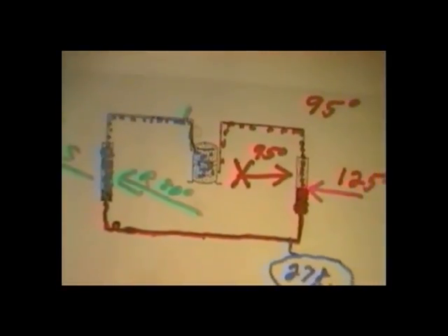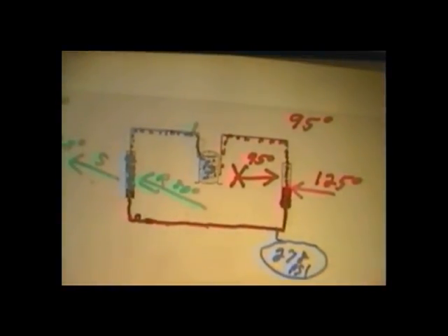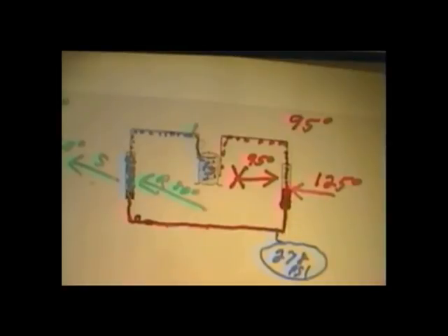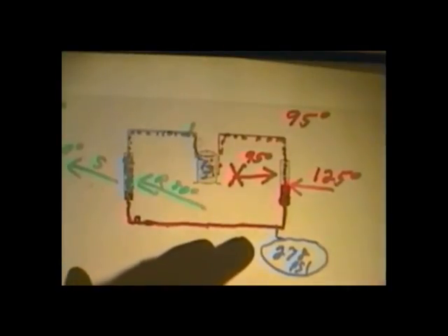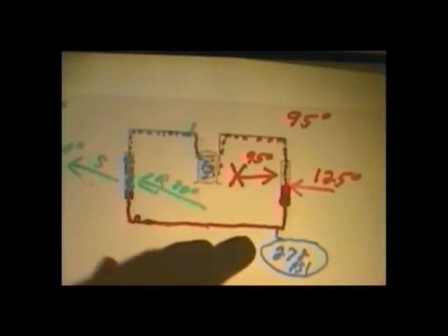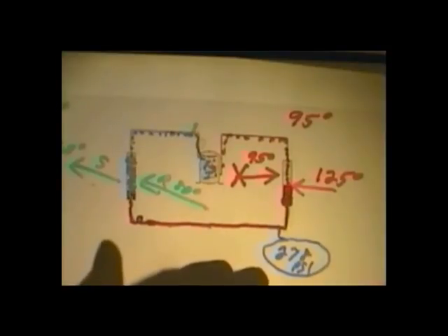So what I'm going to do here is, I'm going to say that we put our pressure gauge on here, and I read 278 psi. That's how I know that the temperature of my condenser is 125 degrees. I take my pressure from my gauge, and I have 278 psi, and I use a PT chart or read the gauge, and it says, hey, 278 is 125 degrees. Saturation temperature, condensing temperature, change of state temperature.